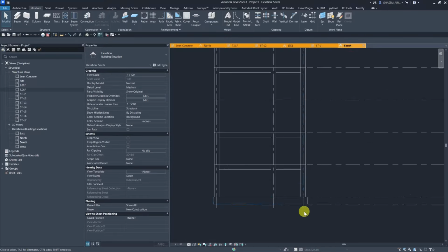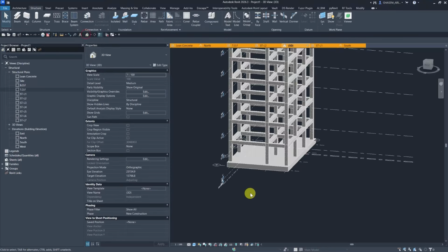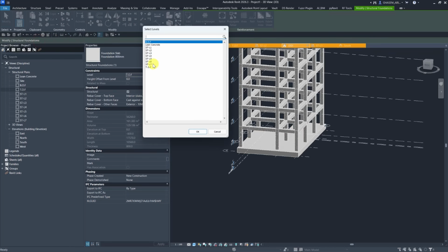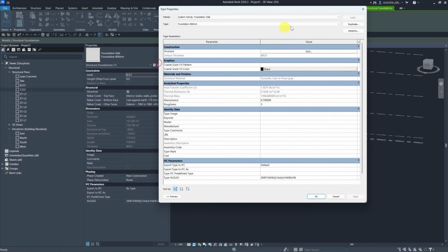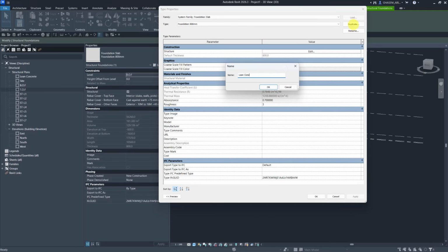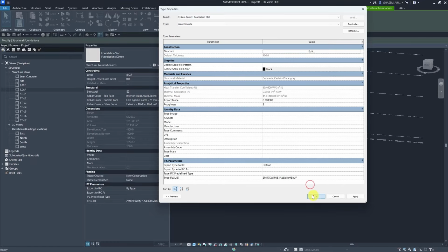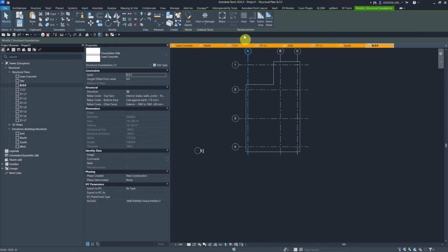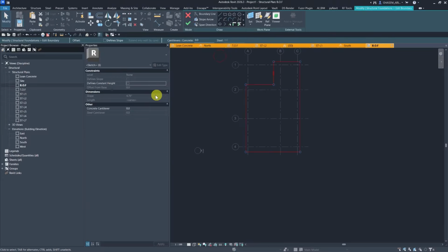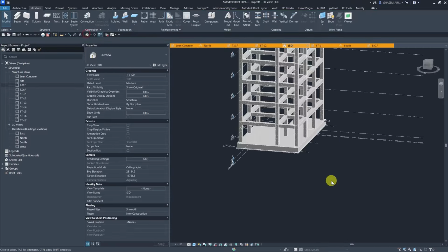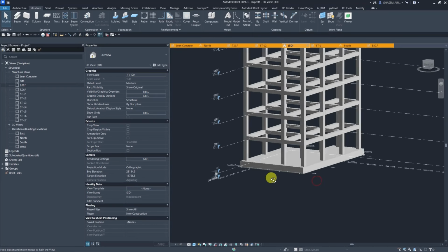Great. Underneath this, we need a concrete layer, more precisely the lean concrete. So what I'm going to do is select this and copy it, then paste it on the BOF level. Now, give me a duplicate. Lean concrete, thickness 100 millimeters. And guys, we also need like 10 cm of protrusion for this from all sides. So I'm going to select this whole thing and set this on -100. Finish. And now we got the lean concrete layer as well.